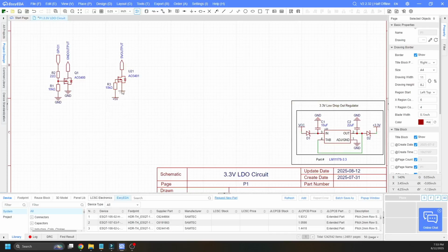If we have a 5 volt pull-up resistor right here, that means we have 5 volts across this resistor. If I was to bring another GPIO over here, like we did here, and plug it in, we would actually have issues because you are now introducing 5 volts to the microcontroller's logic, which can only handle 3.3 volts.